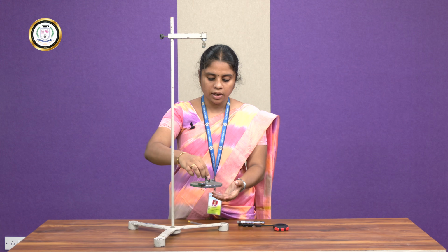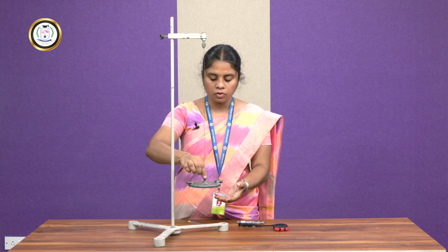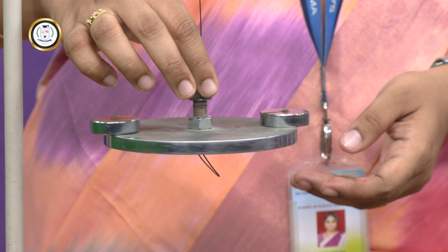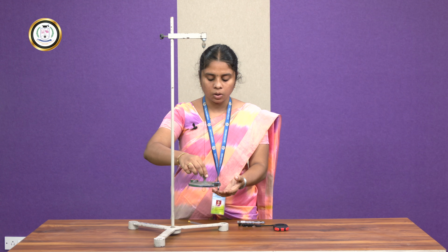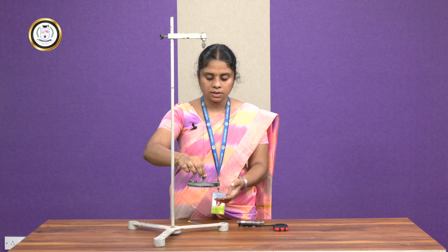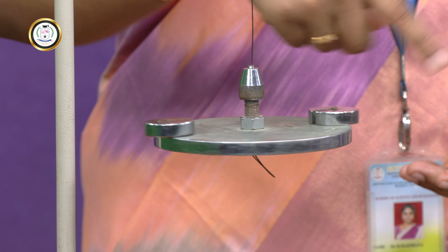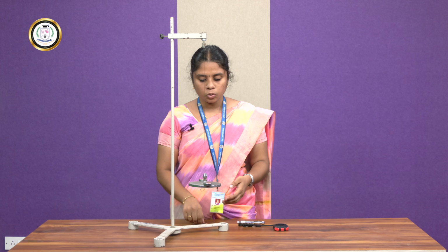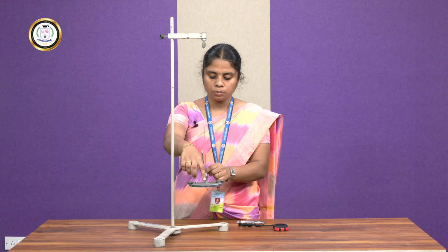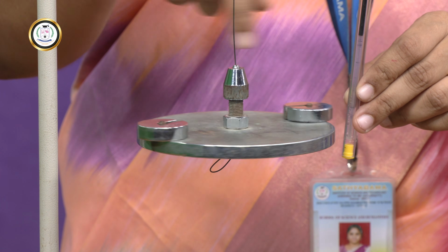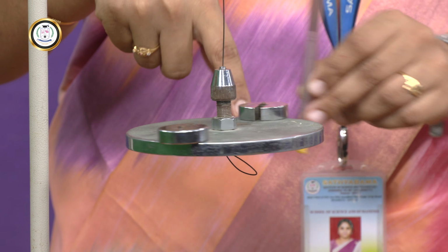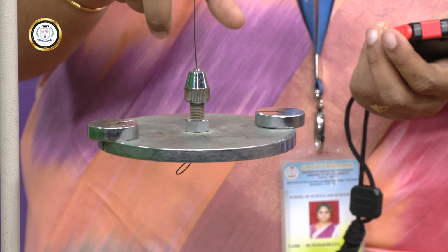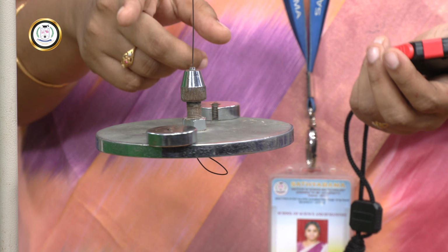Now start giving some couple to this circular disc. A very small amount of couple is required to obtain successive torsional oscillation like this. So now you can see it moves from an initial position to a new position. Again this mass comes back to its initial position. So in this position C also we can produce a torsional pendulum. Again start your stopwatch, see the time taken to complete 10 successive oscillations. Note down the time period for 10 oscillations.